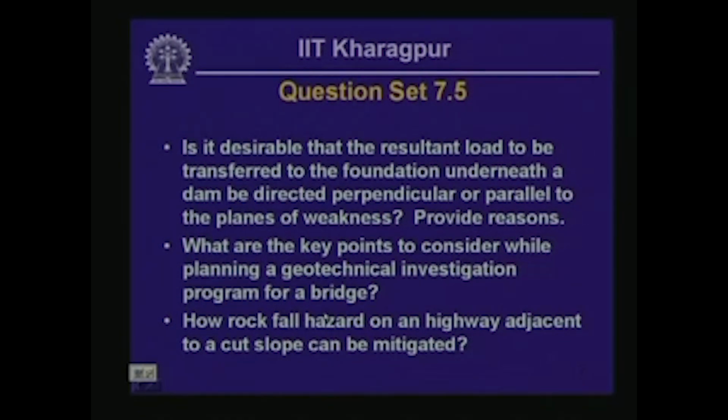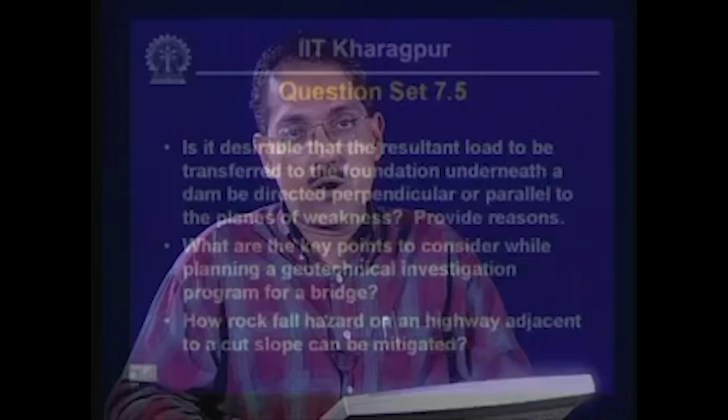So it is preferable that the orientation of the resultant of the load to be transferred be perpendicular to the bedding direction, number one. And the second thing that needs to be emphasized at this point is that the aerial extent over which bridge foundations transfer the load is relatively small in comparison with the dam to foundation contact. As a result, we need to be really worried about the local variability of the load bearing stratum.